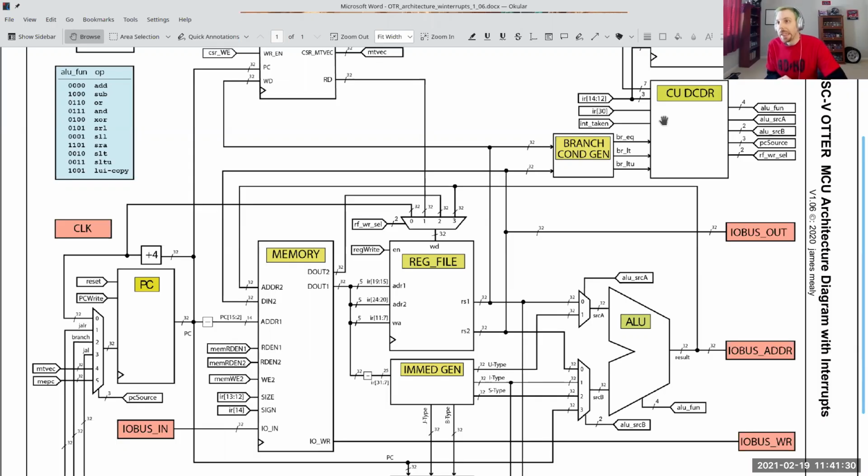More like, yeah. Right. And so sometimes it's not whether it's too many, it might be how, right? Like if one feeds into the other. So this goes back to, right, case statements tend to make big muxes. If else's tend to make chains of small muxes.